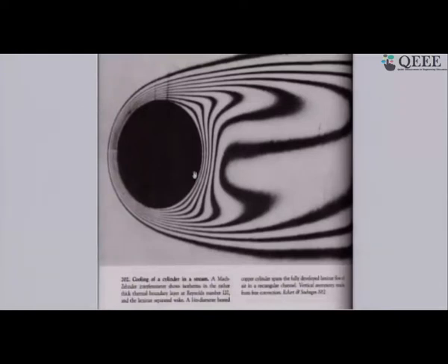So this picture, and if we extend that to all the other pictures that we saw, will give us a total picture of what happens locally over a cylinder. And then if we do an area weighted average, we can calculate the average heat transfer coefficient over the cylinder. And that will be equated with Q = hAΔT. So let's now see what type of categories of flows we can have for a cylinder in cross flow.